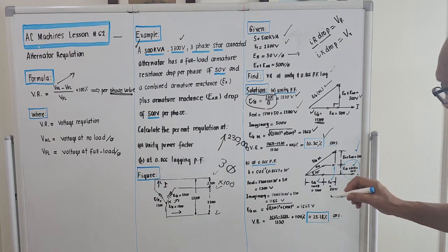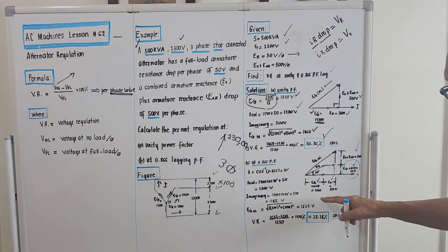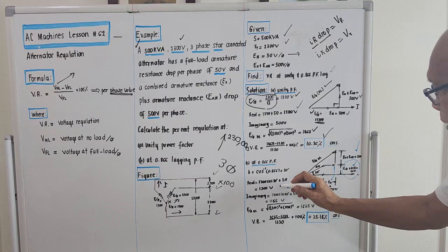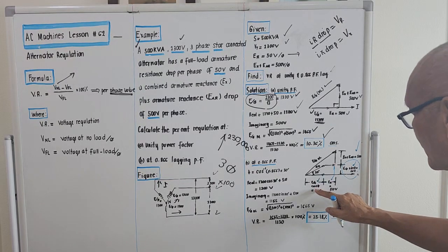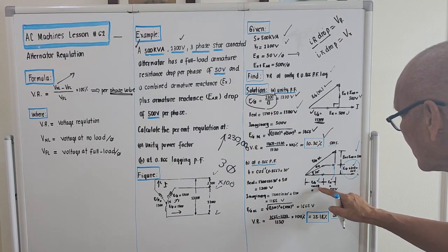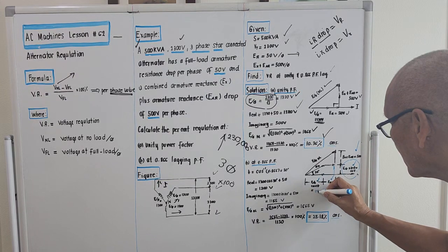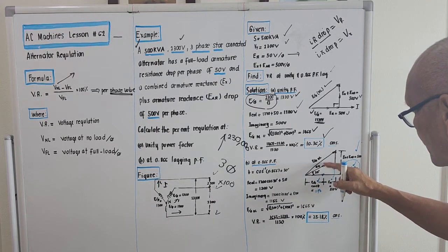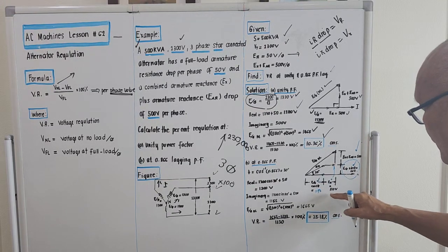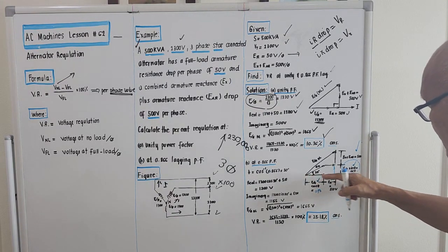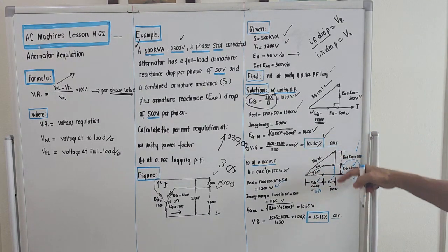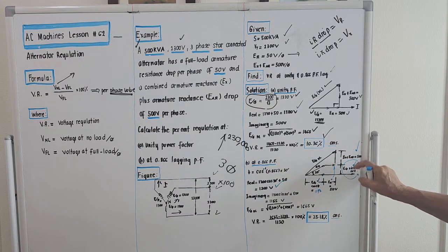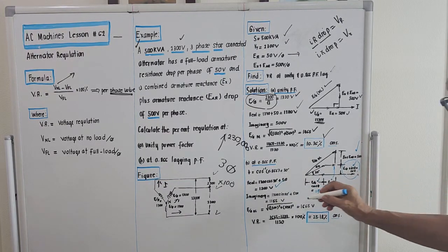Okay. The real part is 1,200 plus 50. It's not 1,200. This is 1150. 1330 times cosine of 30 degrees is 1150, plus 50 volts. The sum of these, they are both real, is 1,200 volts. For the imaginary part, the vertical component, it is the sum of voltage per phase sine of theta, which is 665, plus 500, and that is actually 1155 volts.